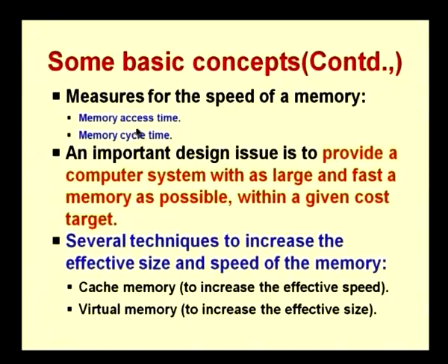We normally refer to that as setup time, and you have to hold it in that place for some time. We call that hold time. So, setup time and hold time are two other terms which are used when we are talking about memory with respect to write operations. But normally when you say cycle time, it is with respect to both read and write operations. So, for our understanding, we can just worry about cycle time, and need not worry about the other things.